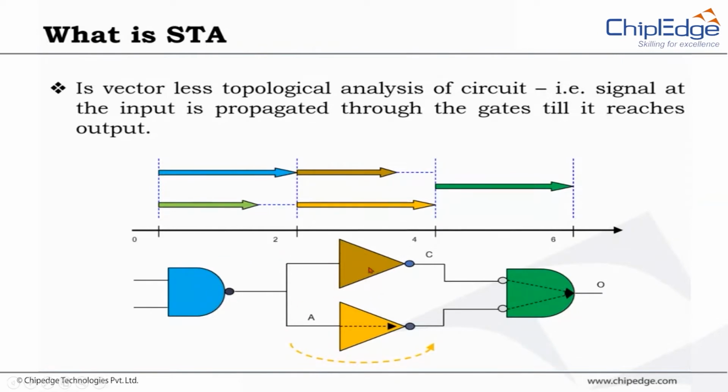So that's what this is trying to represent for you, the possibility that the path from upper input to the output of the first gate is a longer path, let us say. However, the upper inverter is a shorter path compared to this guy. And then let us say, for example, the input to output of this gate is, let's say, the same value. It's just an example. So you will find that there is a certain variation possible, even though you're looking at simply 4 gates here. I mean, 3 levels of delay here.